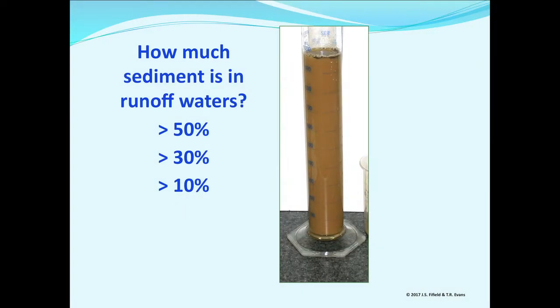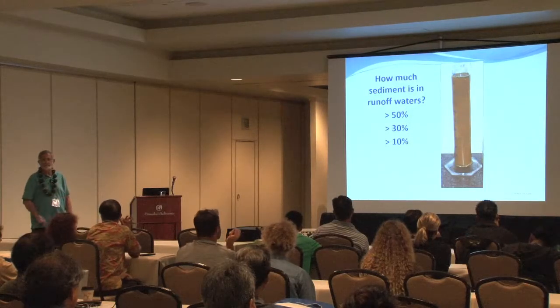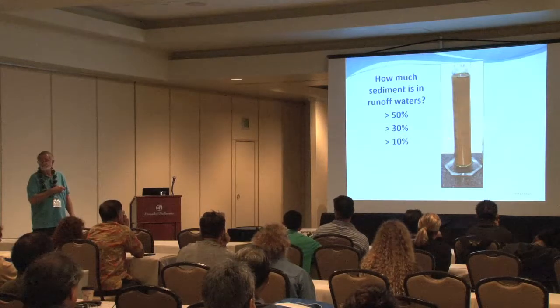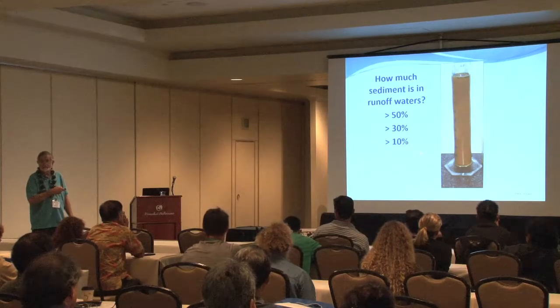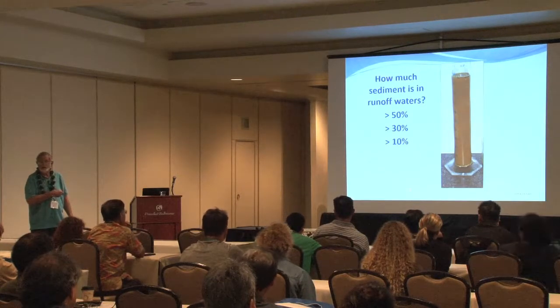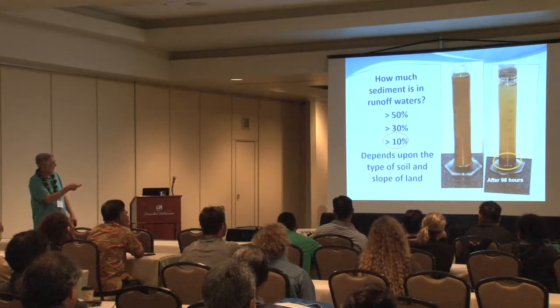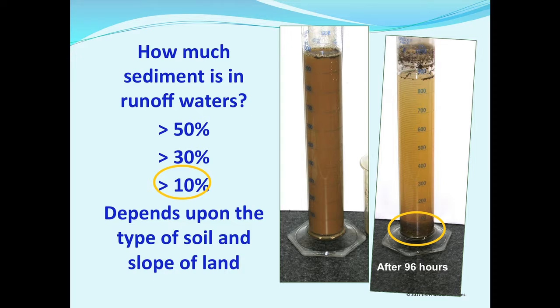Now, here we have a beaker of water, and you have no idea how much sediment I put in there or soil I put in there. But what would be your guess of how much of the total volume here is sediment? Anybody want to take a guess at 50%? Good. Anybody want to take a guess at 30%? Good. Anybody want to take it at 10%? Yeah, that's the one. Anybody want to say, I don't give a darn? Okay. After about 96 hours. This is what I'm saying. The predominant amount of volume when you have runoff, maybe 5, perhaps 10% might be sediment. The majority is water. That's a heck of a problem to try to take care of for sediment control, isn't it? You've got to get rid of water. That's the thing that comes out of it.